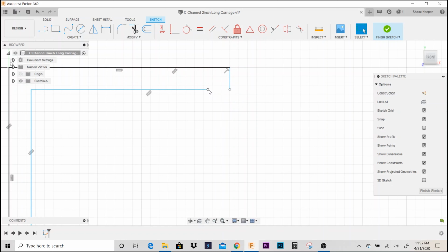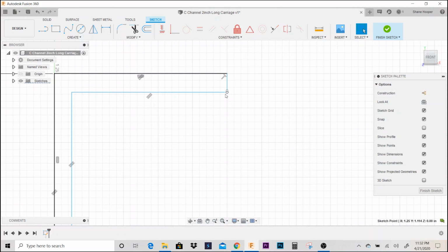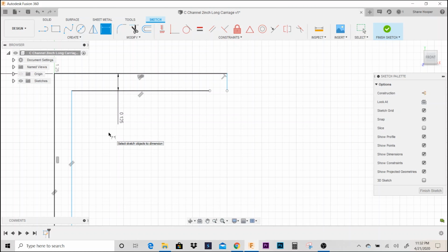And now I can move this cursor right there. Now see how it moved on me? Let's hit Control Z and undo that, or just hit undo. One thing you can do to prevent that is we can reconstrain this dimension. Let's make it 1/8 inch. Now if I hit escape to exit out dimension, I can drag this over to that endpoint.